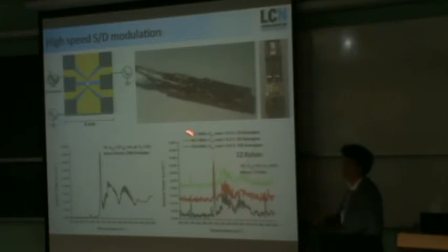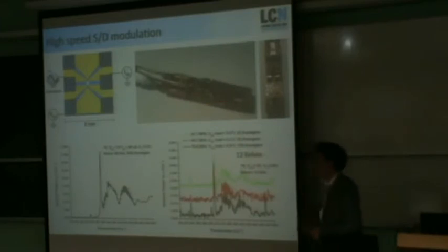So here we're actually limited by hardware, but we're able to get a very reasonable optical response using 80 megahertz modulation on the source drain contact. So already quite exciting that we can detect terahertz at that kind of speed with just a very simple transistor device.